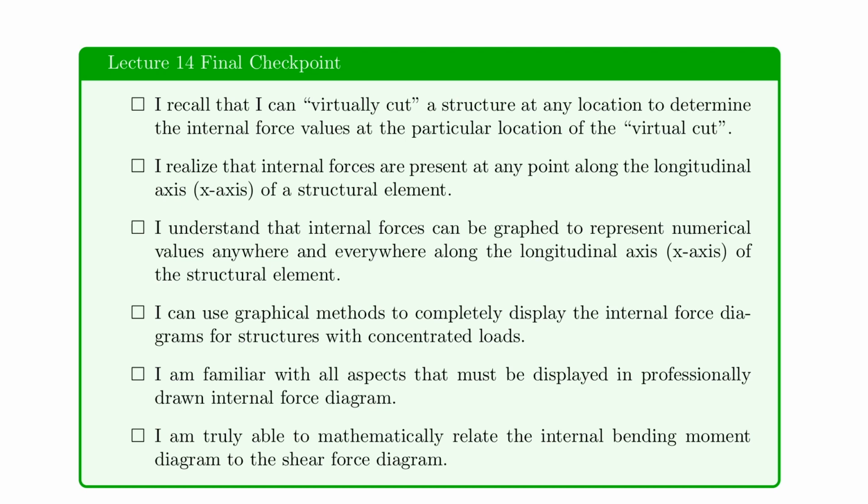So the first thing I need to understand is that I can really make a virtual cut anywhere along the structure to find the forces at that location where I cut. So it is important that we understand that it's really any location, and the reason that I'm doing that is because I want to find the values for the internal forces at that particular location.